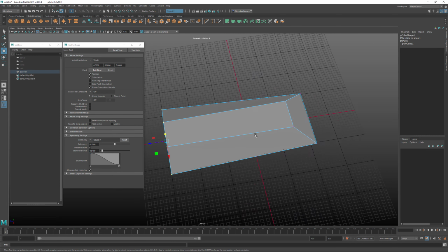So I wasn't going to get into this, but as we move away from the camera, this is a really annoying problem with Maya, that it starts to draw these really black kind of gunk things. And if it's too far away from the camera, it just starts to clip it out like that. If we select our camera, let's hit Control A to bring up the attribute editor. That's because of this near clip plane or the far clip plane. So as it disappears, there's a clipping plane for where the camera draws out.